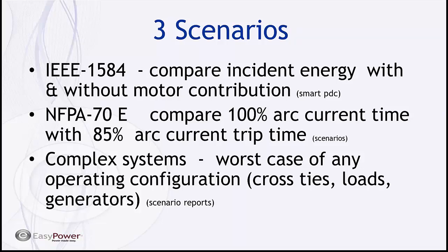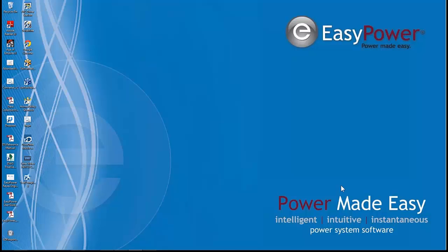There's the requirement to compare each of these configurations if the system will be spending any time running in that mode, to verify that the arc flash incident energy that's being calculated and labeled for is considered in your labeling scheme. So let's jump into the tools and talk about each of these briefly.